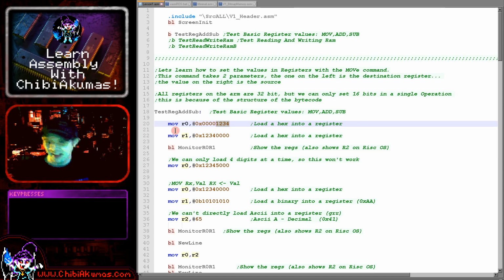And it's like, well, that's kind of part of RISC, and RISC-V is the same. There are limitations in the same way. Now, some assemblers may have special commands that will actually allow us to load the full part, and they will actually do things internally and split the command up automatically for us. And that's where your listing file can be quite handy. But as I say, in this case, I wanted to prove the point that it doesn't work, to show, you know, this is the limitation. And so don't be surprised if you try and do this and it doesn't work.